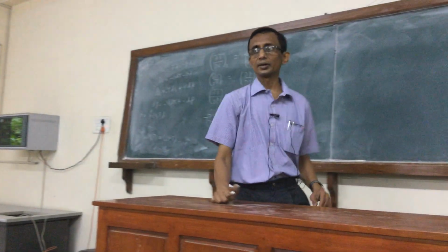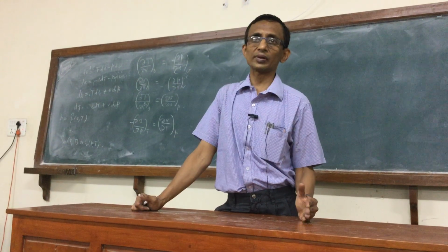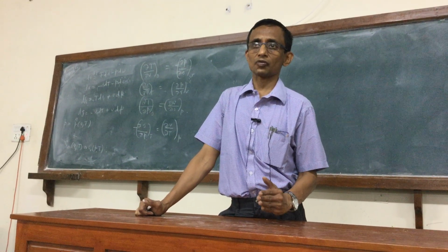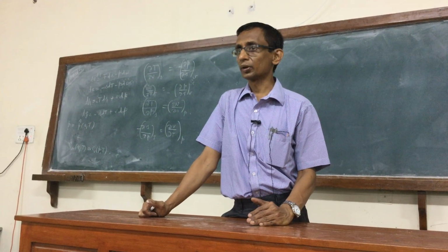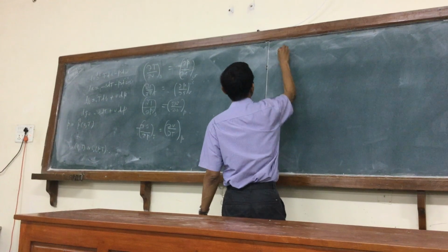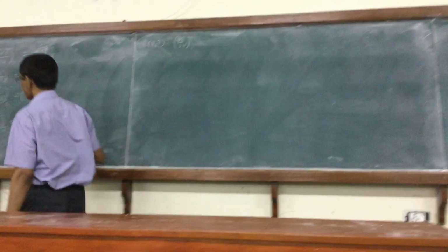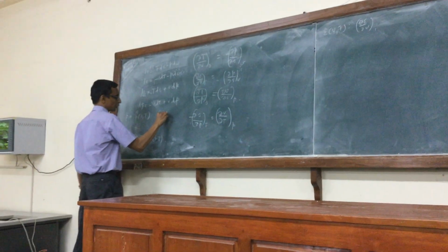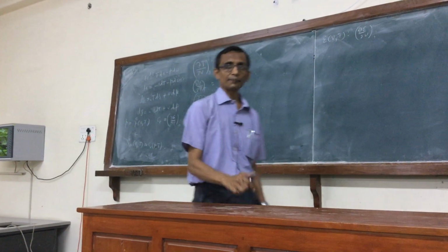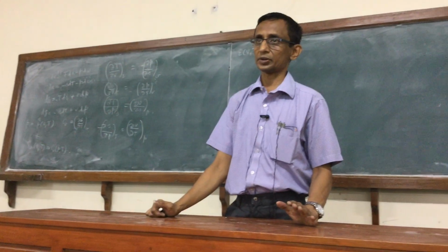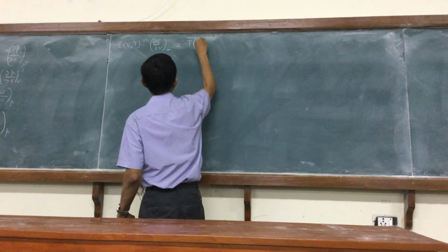So that is the energetic data. P is a mechanical data. So some of the coefficients we will see are directly expressed in terms of the equation of state alone. They can be determined by the equation of state alone. So starting from E, suppose we show dE by dV, and as far as definition is concerned, we define Cv, the specific heat at constant volume, as the derivative of the internal energy with respect to temperature. So now dE by dV, we showed yesterday that this is...